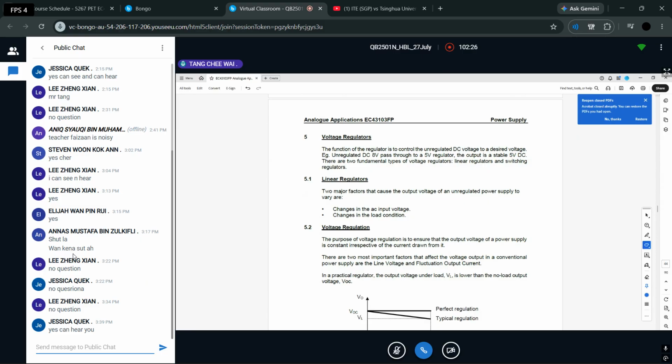You cannot have a power supply where your voltages fluctuate. Fluctuate means go up, go down, and that means not stable. If it's supposed to be 5 volts, it's 5 volts. You cannot suddenly drop to 3.5, for example, or go up to 6.3 or whatever. So voltage regulation comes in to maintain the voltage at a constant value, whichever value you want, but it has to be constant.